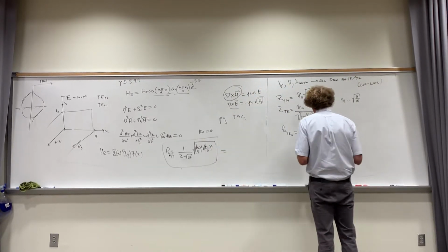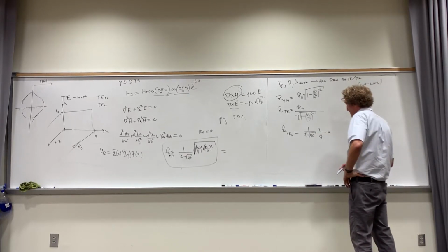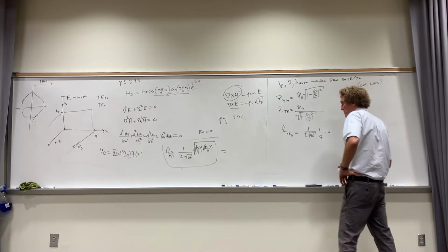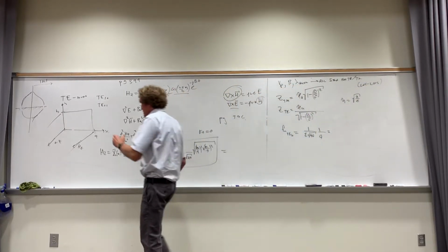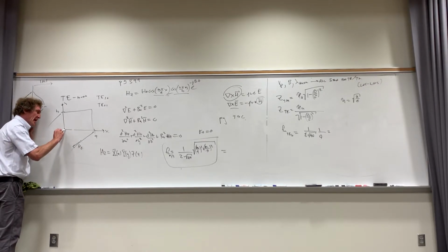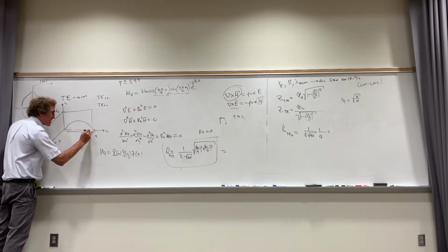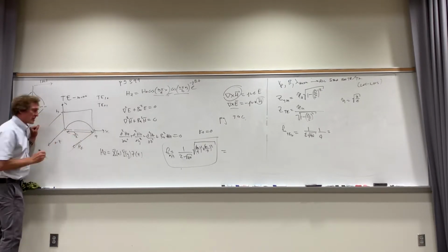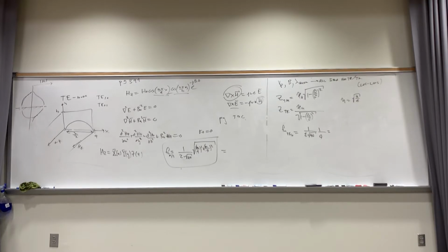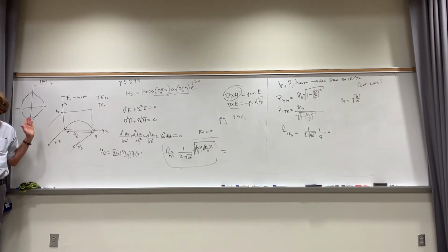Now, what that actually means is this. If you just bear with me on this one. When you look at a waveguide, and you look from 0 here to here, what it means is a half wavelength will just fit there. So this would be exactly λ/2 at cutoff. And that's the lowest order frequency. Does this make sense to you? The field has to be 0 here, has to be 0 here. At cutoff, it's just banging back and forth, right?